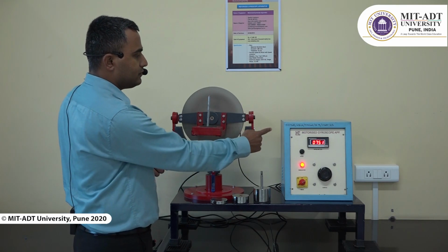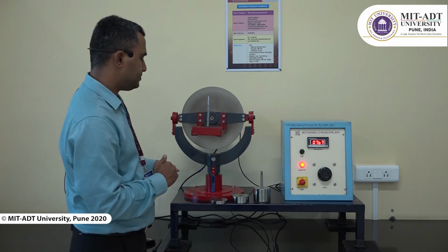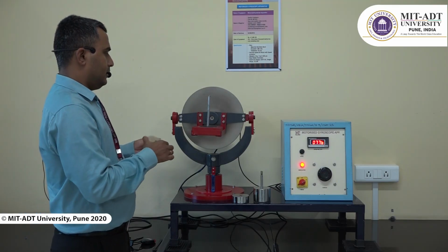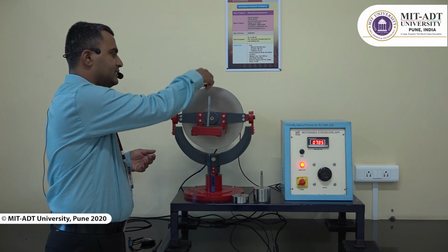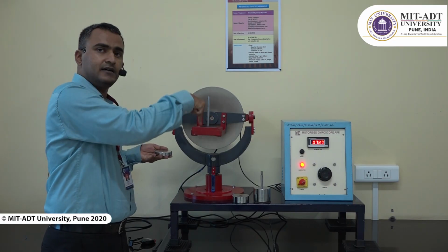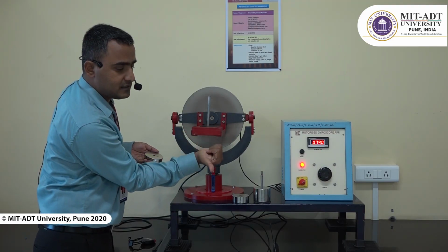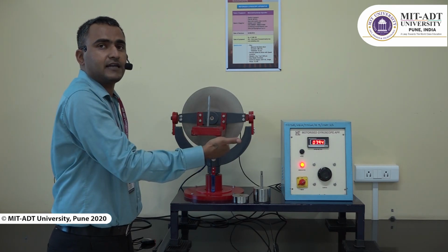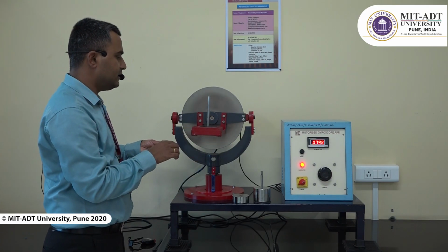Now, if I put the speed around 750 RPM, let us say, then I'll start with mass half kg. As we know, the gyroscopic effect would be similar to the earlier case because I am again putting mass here and the force acts vertically downward. So the axis of spin is going to move downward. It's going to precess downward, and at the same time it is going to show the gyroscopic effect on this side, which was the same in the earlier case. The same thing we can observe here also.